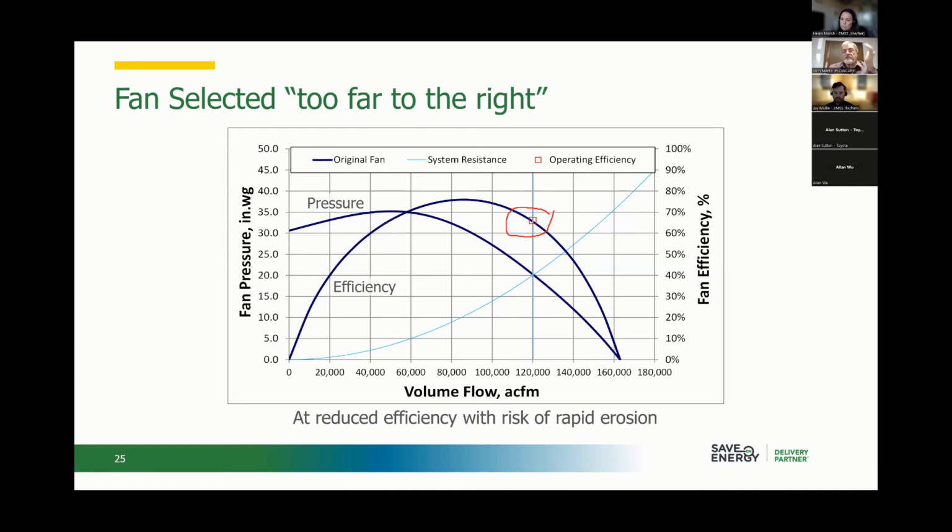One of the advantages of axial fans, and I've got to speak very generally here because I'd soon get taken to the cleaners if I tried to be specific on this, is that they're much better at moving this whole curve off to the right so that you can, once again, get your best efficiency point to line up with your operating point.